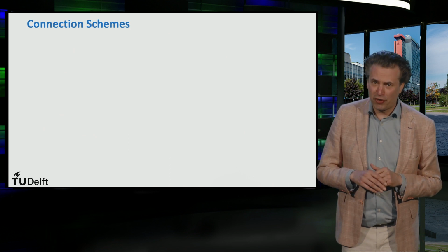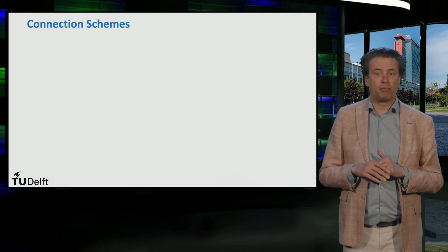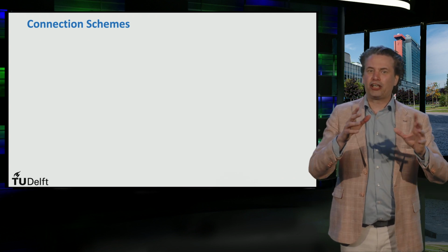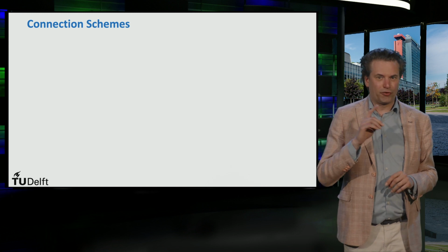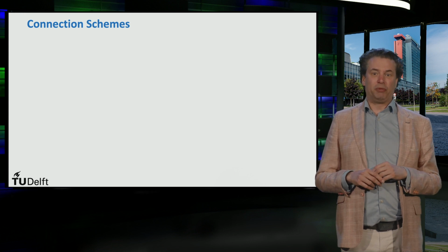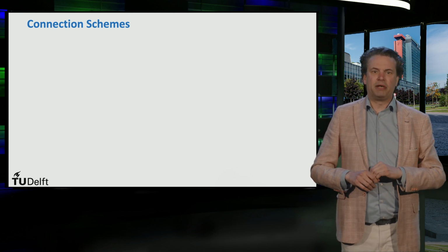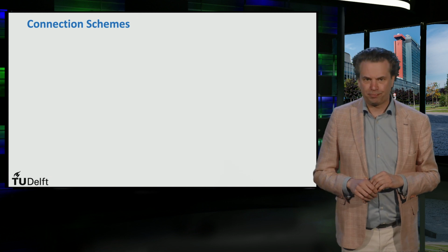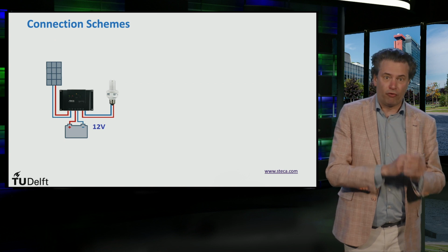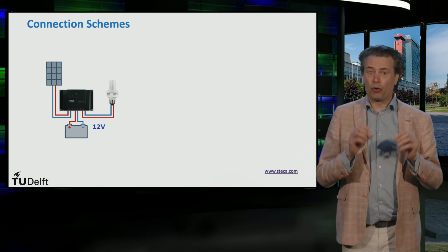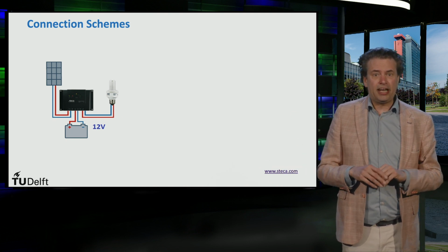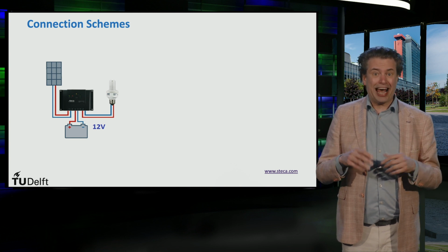Finally, I will talk briefly about a couple of PV system topologies where a charge controller is used. As we know already, the charge controller is an important component in an off-grid PV system. So when deciding on the type of charge controller to be used, a proper decision has to be made for the right type of PV system. For example, when a system with only small DC loads are involved, the charge controller can be the component that brings together all the other system components. They are the PV modules, batteries, and the loads.